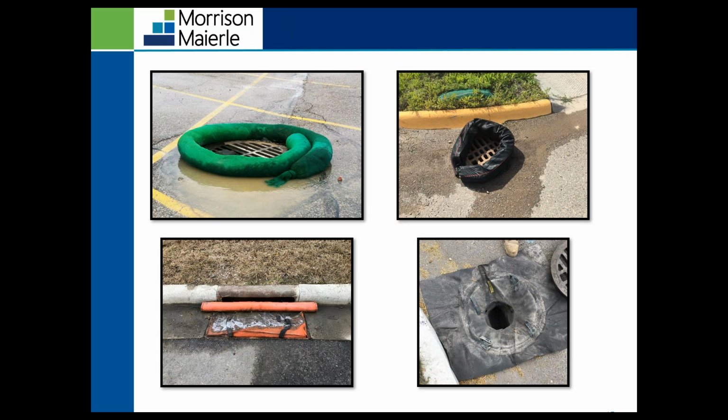With anything, just like that rock sock, whatever you use, you want to make sure that you're doing the inspections for this, making sure that there's no ponding or clogging that's resulting in flooding back into the public roads. These inlets are designed to capture stormwater.